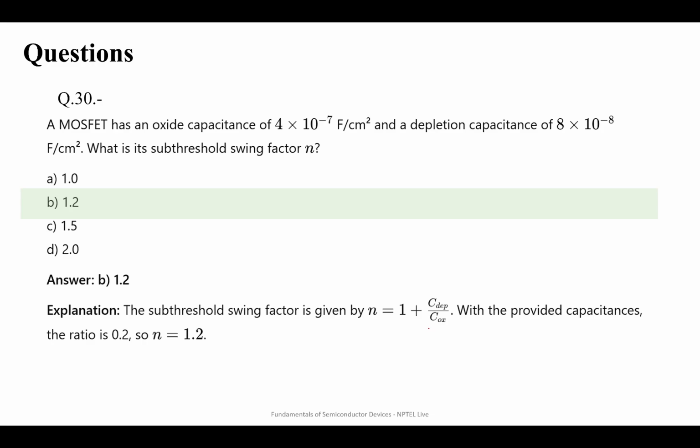That is why we are either reducing the gate oxide thickness or using high K dielectrics. The whole point of optimization of all these short channel effects mitigation is to reduce my off current at VG equals 0 to a minimum.